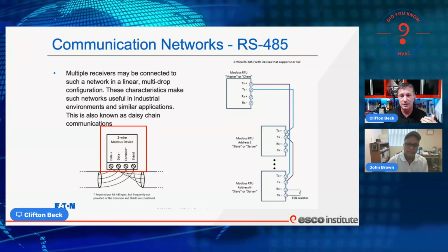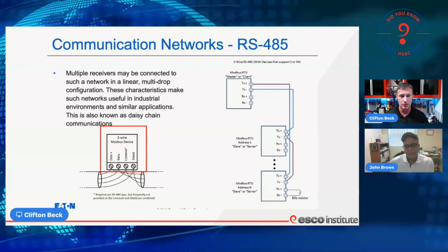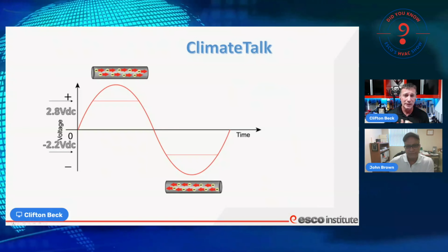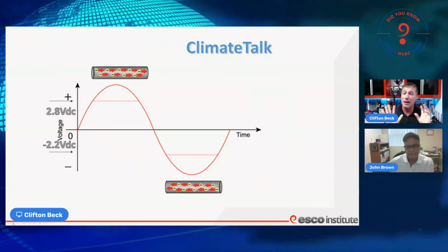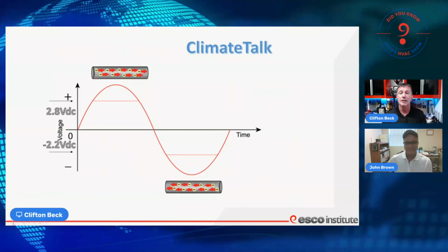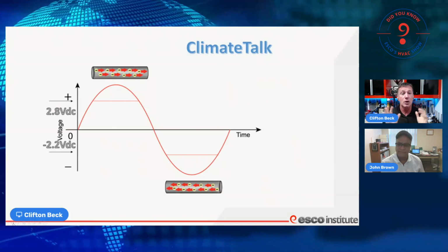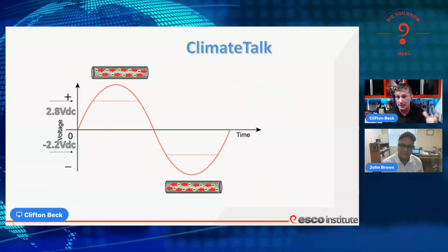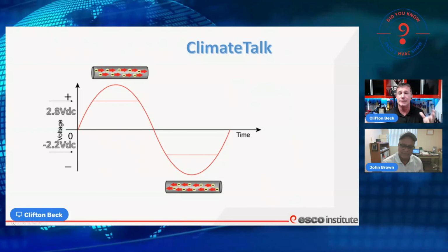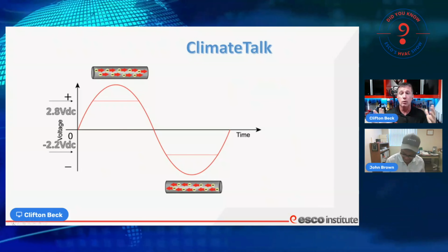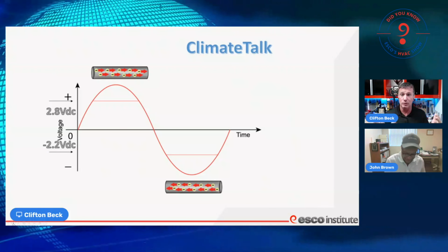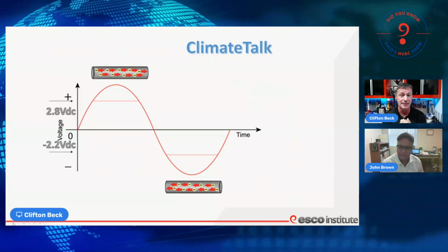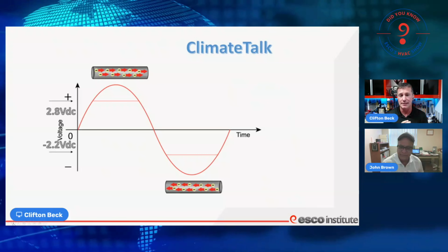We have a positive signal that is in reference to ground and a negative signal that is in reference to ground. So how do we get to that point? Well, it's really not that complicated. It's very ingenious, but not incredibly complicated. We take our AC power source, starting at the furnace or air handler, our indoor unit, which is where our power source originates typically, right? That's where the power supply is. So we take our AC signal, we run that through some bridge rectification. We run it through diodes. We get that rectified into a reduced DC signal at about 5 volts DC.